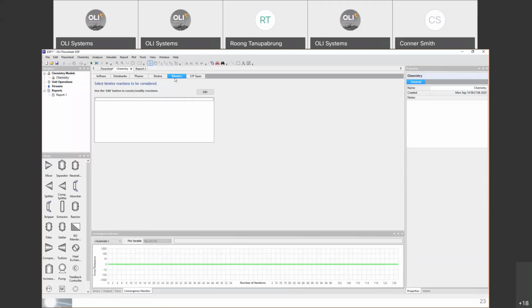By the end of this course, we will learn how to enter or modify this kinetics window here. But you also have that option to overwrite equilibrium reactions and enter your own kinetics equation. We don't do kinetics, but if you happen to have the kinetics, you can always enter them here and edit a specific reaction that you may want to overwrite.